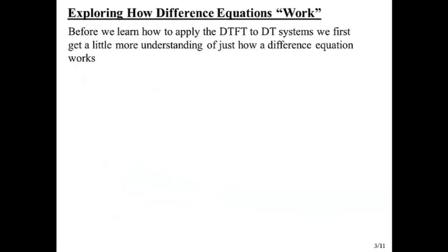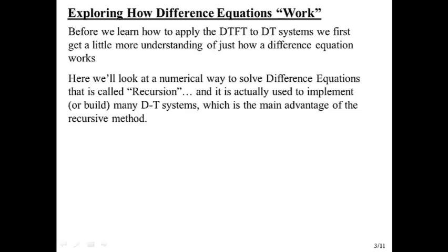So let's take a look at how these things work. And before we get into the DTFT approach, we should just have a little better understanding of what makes a difference equation work. So there are some numerical methods that we can use to solve these difference equations, and this is what's known as recursion. We looked at that method earlier, quite a long time ago. And not only is this a way to quote-unquote solve the difference equation and find out how it behaves, but this is really how they are implemented.